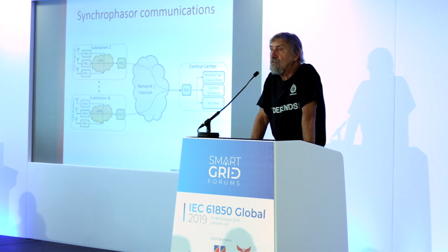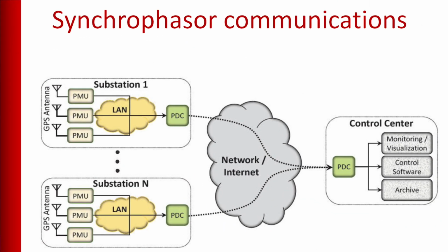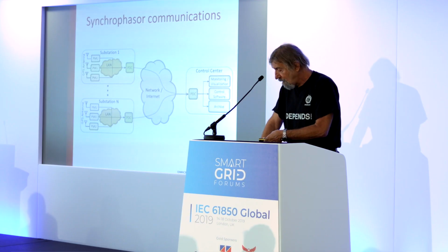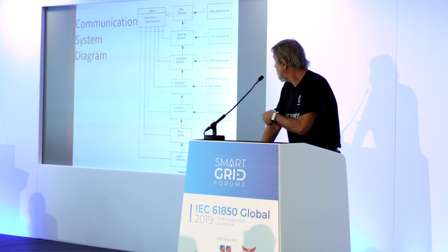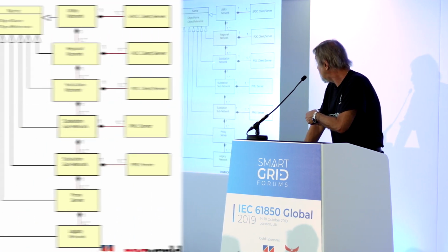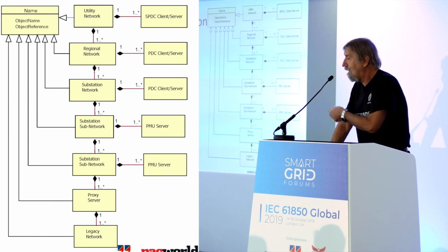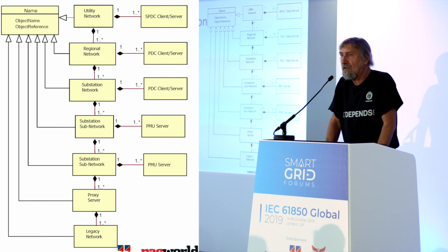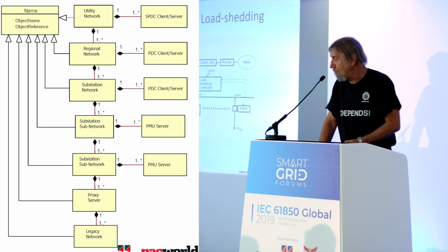And the next thing we need to understand is that, as I mentioned, it doesn't make sense to send the individual synchrophasor measurements from every PMU all the way to the central or regional center. What we do is we use the concept of a PDC, a phasor data concentrator that collects the data from several PMUs and sends a single stream of data. And the hierarchy of this can be quite complex. So you see here we have local PDC and regional PDC, and then a PDC for the SIPS or for the control center, etc., etc.